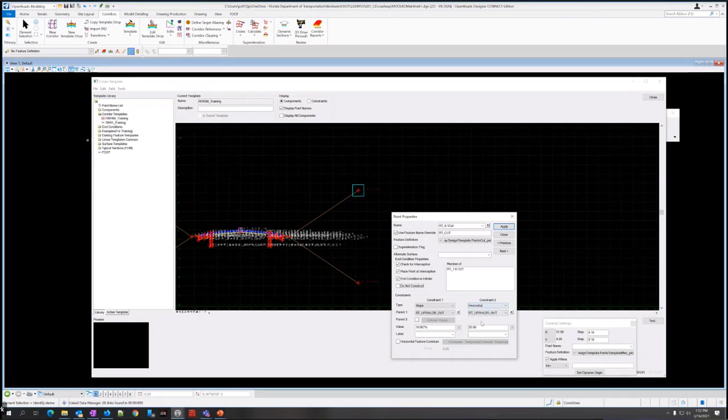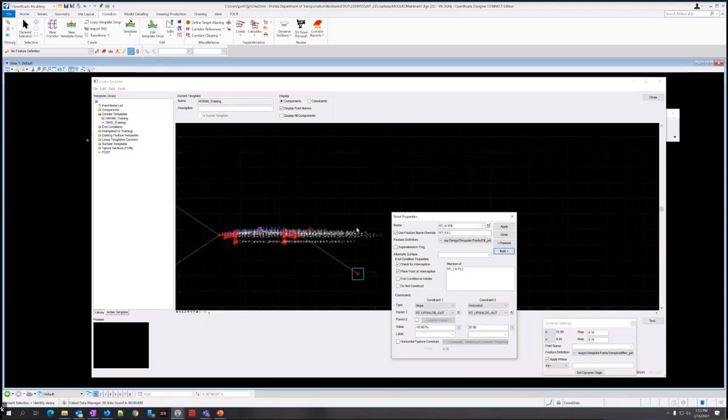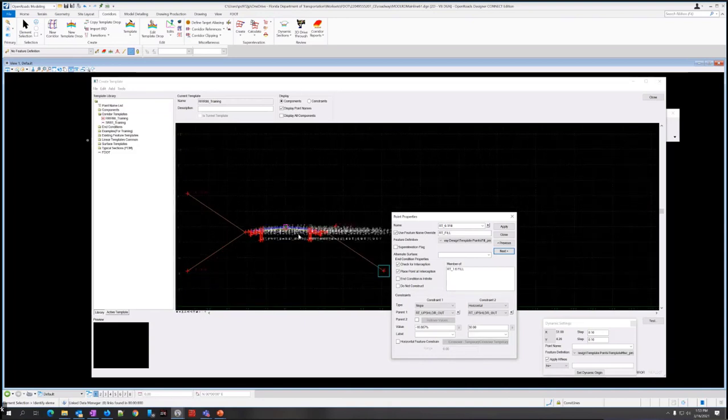And then we're going to change this constraint on the horizontal. Set to 30, because it's infinite. We can shorten it up. So we're just going to change the horizontal down to 5 feet. Click apply. Nice and short. So I could close after hitting apply, but I could also do next. And this will usually take, I think it's the order that you put these in.